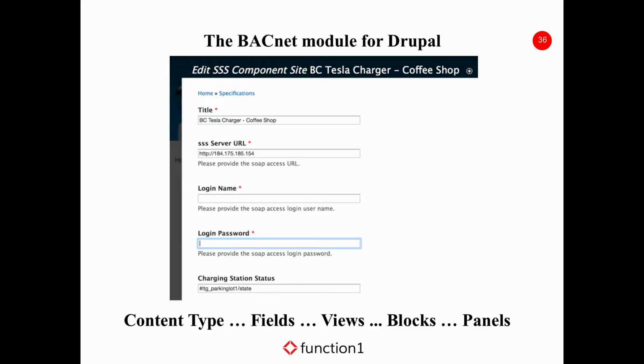They're both essentially the exact same module, but the BACnet module is made to actually connect to the system. The SSS module pretends that it's connected. So we provide the SSS module with a sample set of data so that you can actually play with it and create your websites without having to have the live connection. Both exactly the same, but what we're asking for is the title. We need to know the URL where the BACnet server is located. The building automation guys will give you a login name and a password.